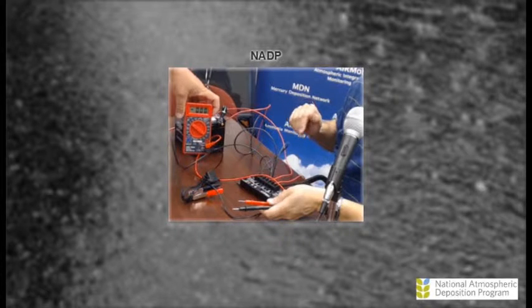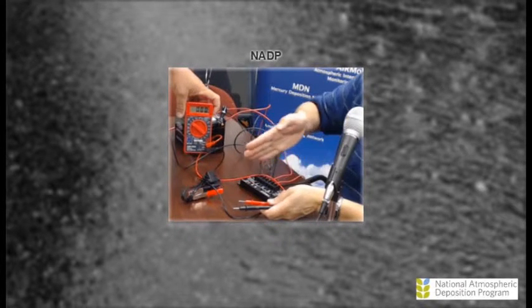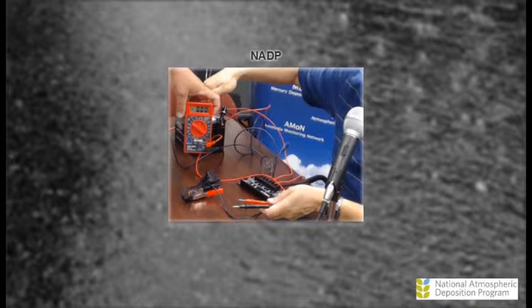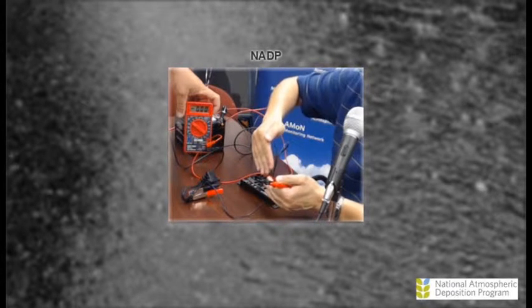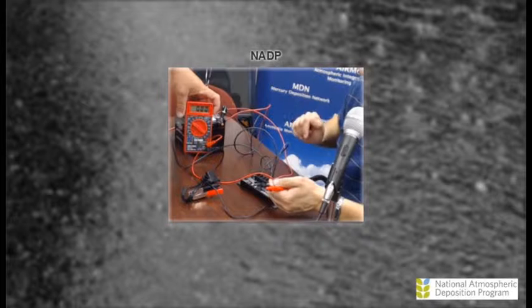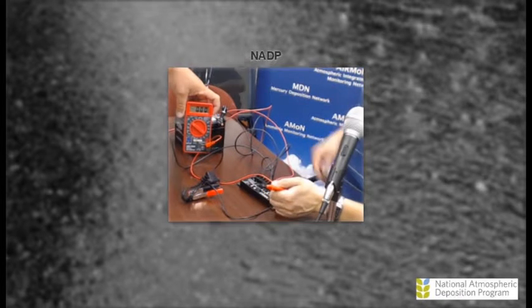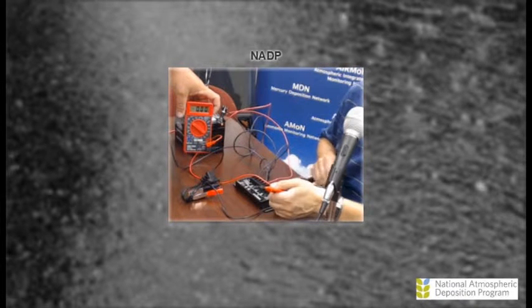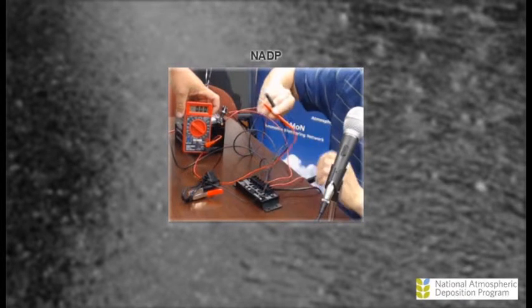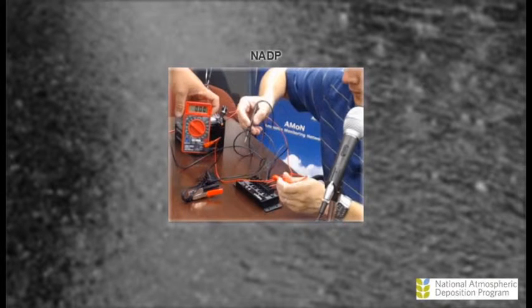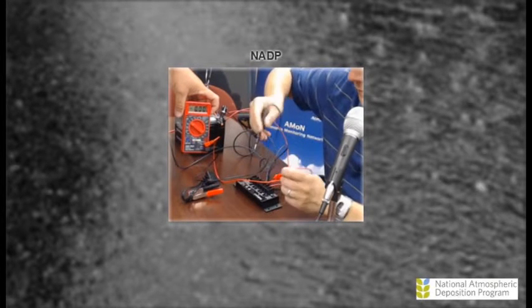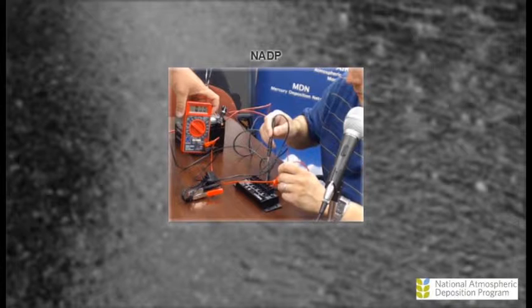Okay, so the blocking diode, as you'll recall, normally the power is coming in from the panel and out into the battery, and the blocking diode is the gate to keep power from going in reverse. So what we're going to do is disconnect. I'm doing this under the table. I'm just going to unplug our solar power lead, and I'm going to be checking for the presence of voltage at the solar power lead.